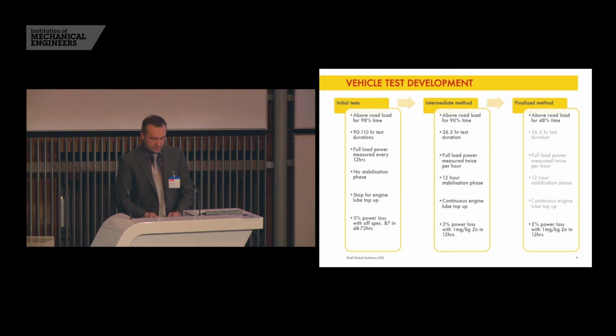And we introduced a 12-hour stabilisation phase, which meant running with detergent additive fuels for the first 12 hours of each test. This allowed us to decouple stabilisation effects of the vehicle, so long-term driveline thermal effects, plus stabilisation of the injectors. We used new injectors for each test.